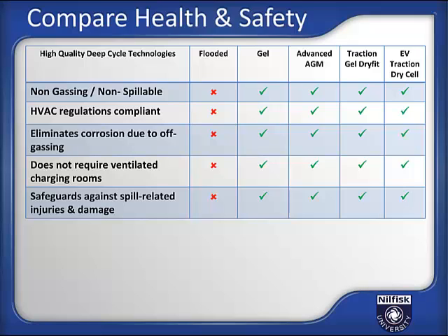Again, just a visual for you to think about here. If you drop a flooded battery and you crack that case, your liquid sulfuric acid electrolyte is going to leak out all over the place, and this is absolutely going to cause damage to whatever surface it's on, but can potentially cause injury to the person who has to clean that up. If you look at all the other technologies, if you drop one of those batteries, the electrolyte has in effect been immobilized.